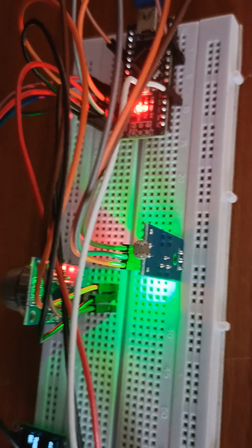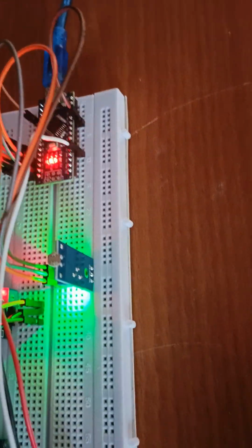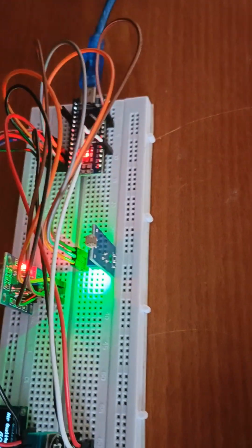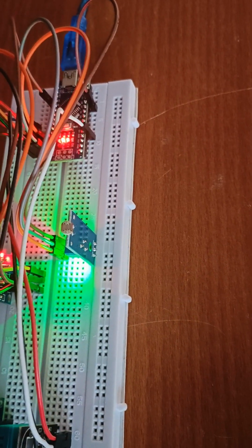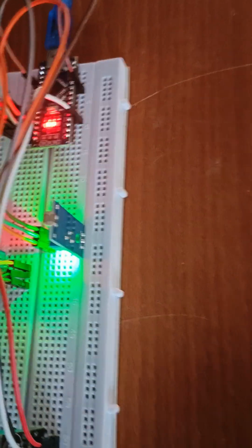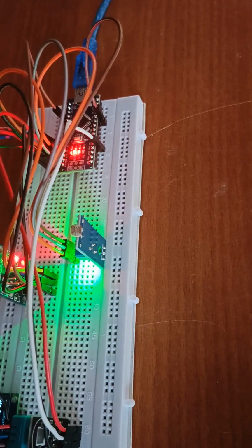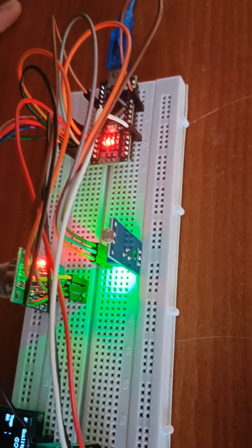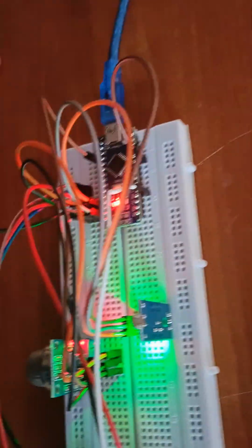It has a typical 10 kilo ohms to few hundred ohms range of resistance, and the operating voltage is generally at 5 volts. Applications are, here we are using it to sense ambient light in our project. It can be used as a light sensing application in automated lighting systems, sunlight intensity monitoring for solar panel optimization, or it can be used in darkness detection for security systems. The board we are using is Arduino Nano V3.